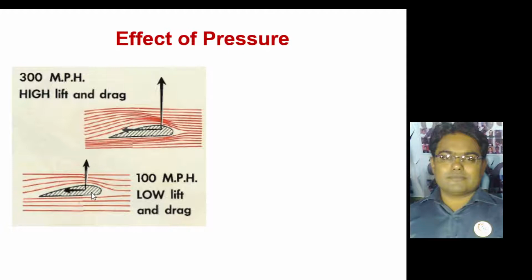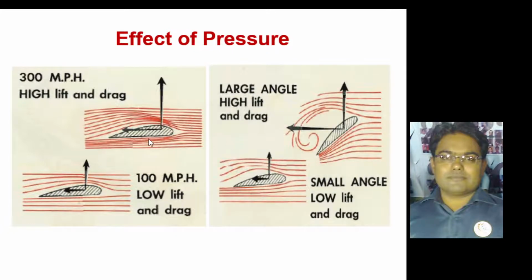So this is one way, either by increasing the velocity of the airfoil or the velocity of the flow. If the airfoil is stationary, we can generate, or we can reduce, the lift. Similarly, if we change the inclination of the airfoil, we can generate a larger amount of lift. So this is the position when your airfoil is basically inclined below the stalling angle of attack. We are having the maximum amount of lift generation. Similarly, when it is oriented at relatively low angles, we'll have a smaller quantity of lift being generated over the airfoil.